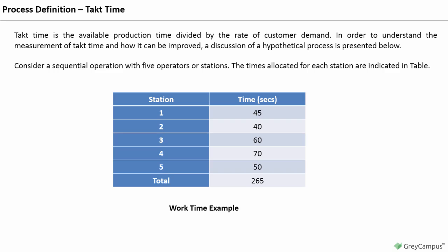One option would be to have some of the time eliminated by moving work to another station. Upon further examination, some thought has to be given to Stations 1, 2, and 5. They do not align with the takt time because of the existing slack time. Only Station 3 has a full 60 seconds of work. A keen Lean Six Sigma specialist will seize this opportunity to review the entire line for another redesign. The total work time used at the current time is 265 seconds. With 5 operators, this equates to 53 seconds on a balanced line.